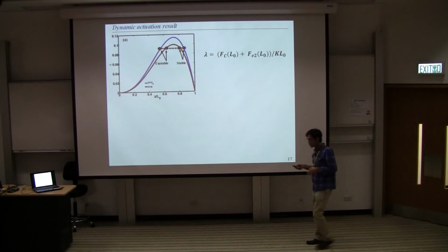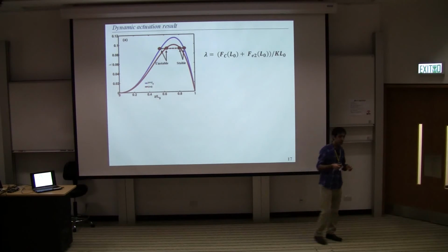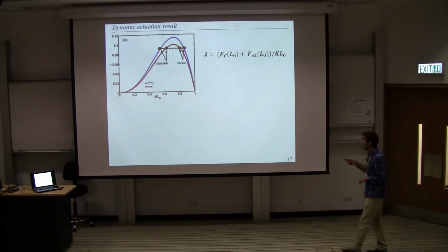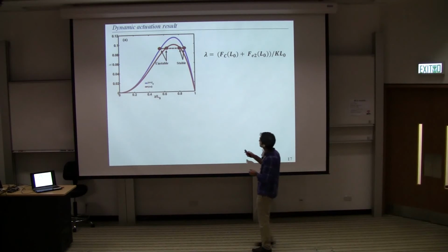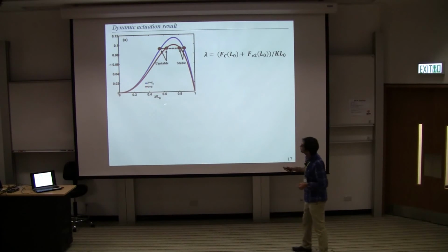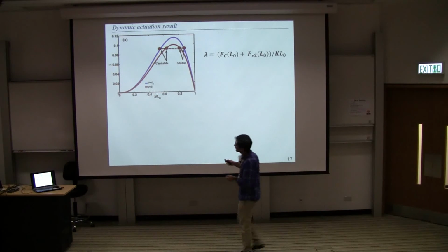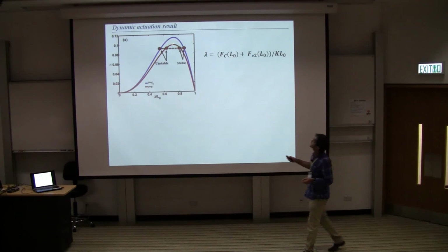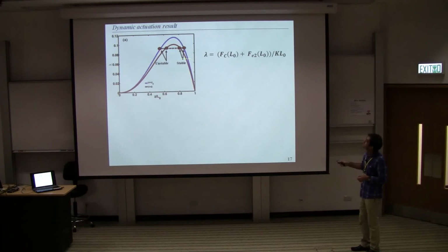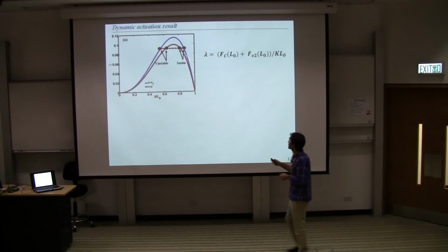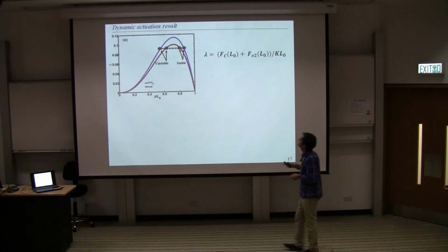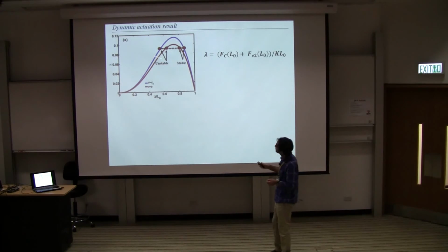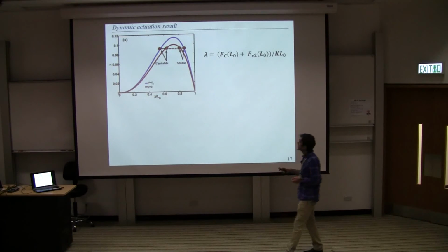which gives us the ratio of the importance of one force compared to the other force, and which is independent of the applied potential. Here the red one shows the case if we don't compensate the contact potential, and the blue is after compensation. It shows that we have a stable and an unstable point. The right side is stable, the left side is more close to the plate, and in this range we are going to have stiction.